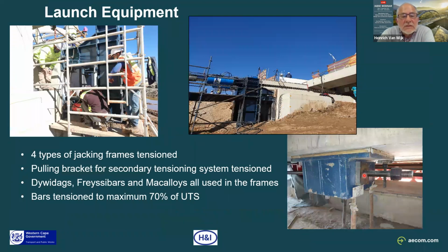So in the design, there were also supplementary force jacks. We actually had two jacks on each side, the primary jack and then a secondary jack in case our friction estimations were underestimated, because keeping in mind that the contractor basically had a weekend to do this operation, and we couldn't permit closure of this major route for an extended period.